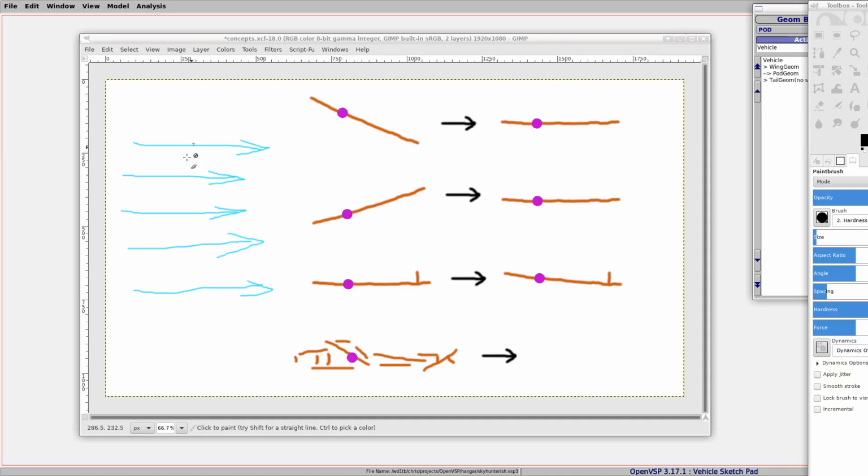And again, we have the air coming in from the left to the right, and this purple thing will be the center of mass of this foam board. So let's say we've stuck a lead weight on here or something, and I think we can all see what's going to happen in the first two of these cases. If the angle of attack versus the wind is like this, it's going to be turned around because there's a larger aerodynamic area on the back, and it's going to eventually end up facing into the wind like this.